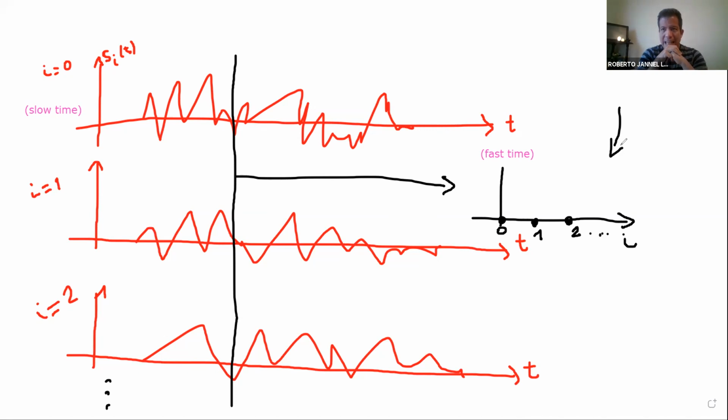And that is the way this analysis will operate. When we do Doppler imaging, the fundamental direction in which we're tracking movement is the slow time domain. Now, remember that we think we have time in the horizontal domain, and that's kind of cheating, because we never have a continuous time signal.